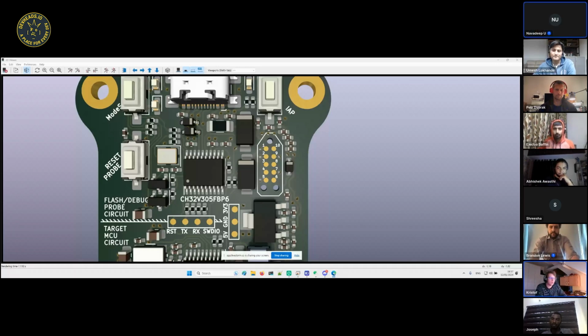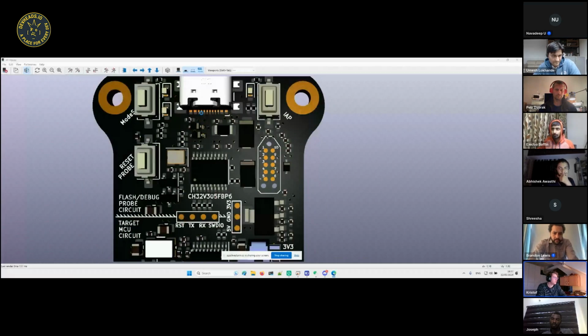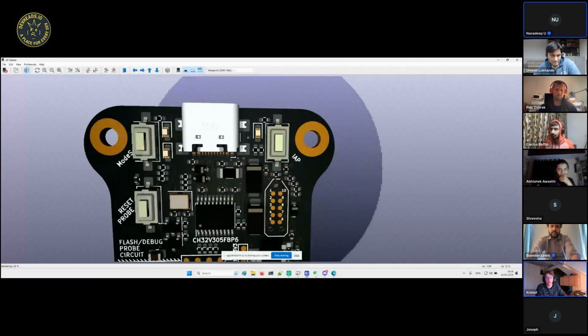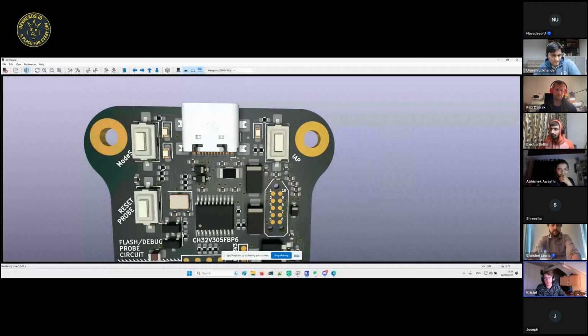It will operate, as you can see, with a USB-C connector on top. But of the USB-C connector, only the USB 2.0 data lines are being used, so it's very simple. I'm not using all the USB-C capabilities, just limiting to the USB positive and negative data channels.